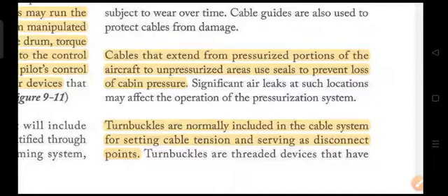We use a type of material which is normally not metallic. Even if it is metallic, we make sure that it is not as hard as the control cable, so that it does not have any impact on the control cable. The fair lead should wear out, but not the control cable.